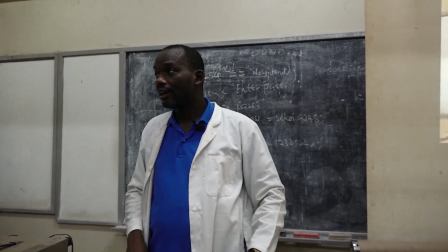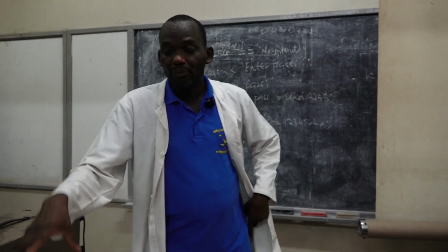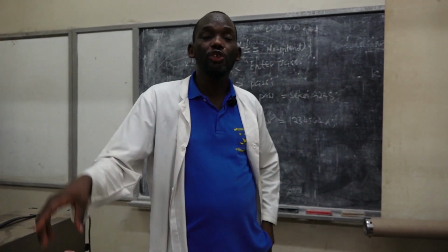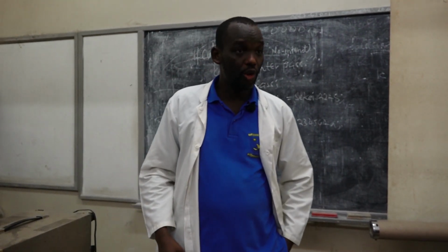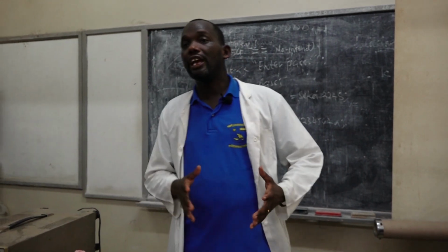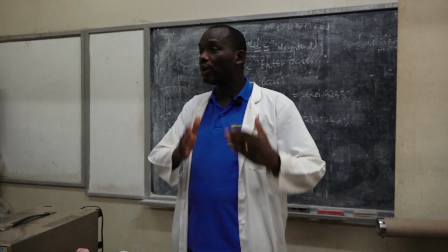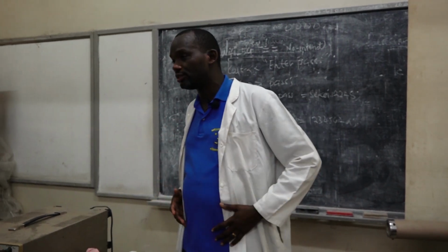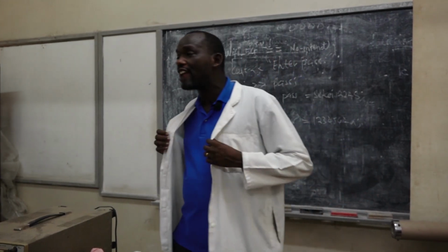It's not clear. I say the maximum voltage that this digital oscilloscope can withstand is 400 volts. In Tanzania, what is the range of the domestic root mean square voltage? 220 volt to 240 volt. Is 240 volt greater than 400 volt?